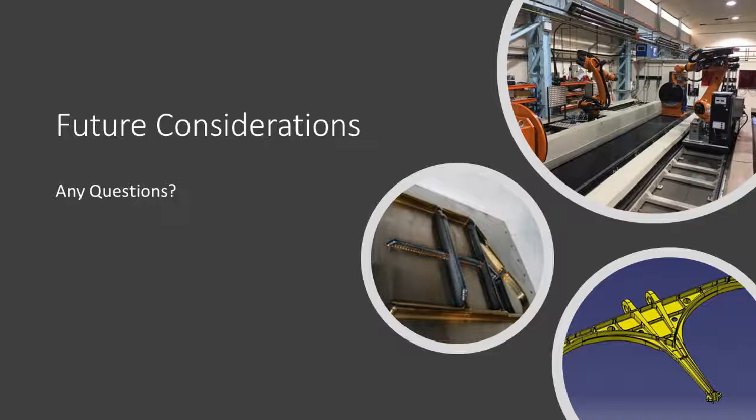Okay. Can you use additive for repairing parts? Yeah, so the Siemens burner tip, that's a great example. So in the combustion chamber, rebuilding parts of the combustion chamber rather than creating a new combustion chamber is certainly a great example of where it's being used now. It's not used on the Tornado's RB199 engines at the minute, but they're an old engine and we're going out of service. But going forward, I'd expect to see more applications of items being recovered rather than the creation of new items.